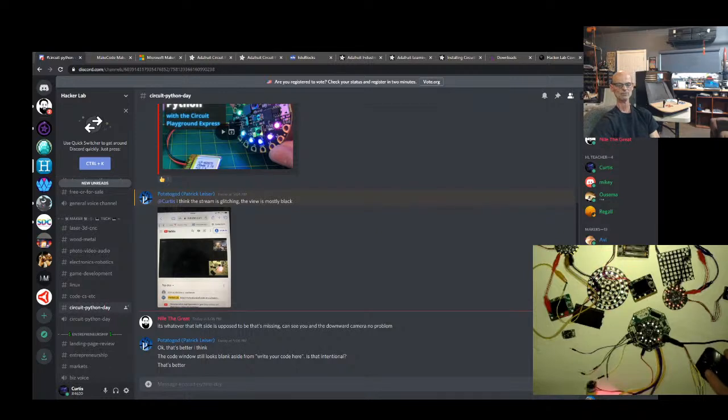You may not be able to see that, but the device has responded in the file explorer. It's no longer called CIRCUITPY. It's called CPLAYBOOT, and it now shows a UF2 in the root folder. This is the bootloader mode, and when these lights are green on these devices, that means you can load these UF2 files in and install them that way. MakeCode outputs UF2 files. CircuitPython itself is hosted on a UF2 file that you have to drag and drop on your device. To do that, you have to have your device in bootloader mode for that to work.